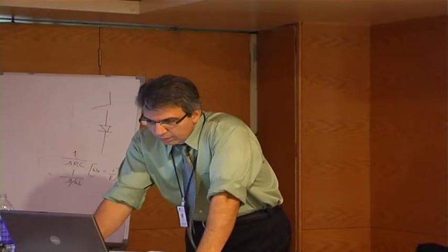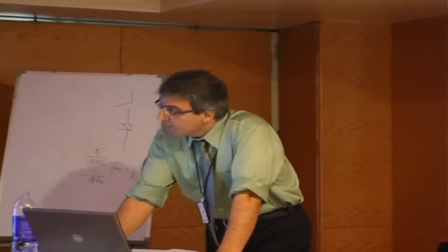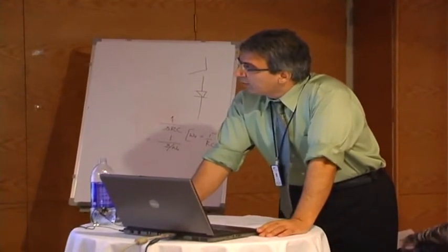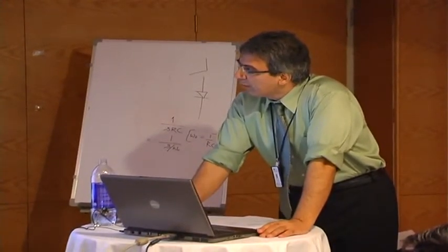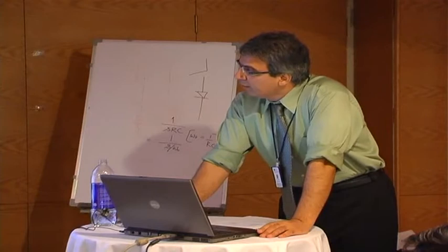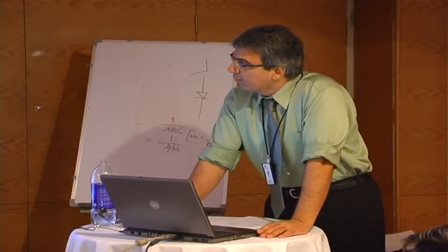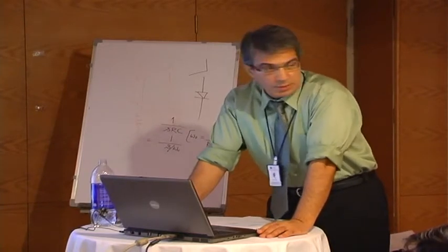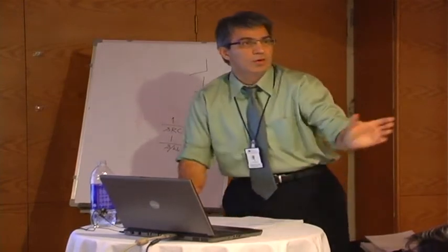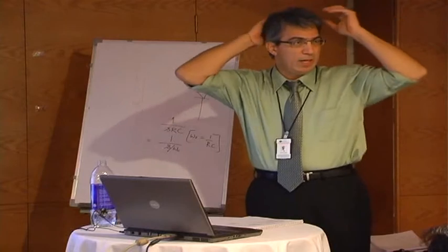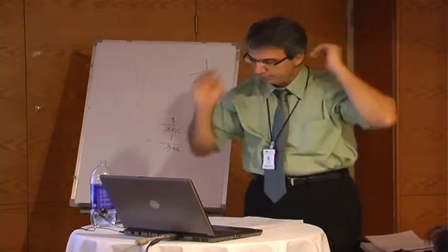Now we have a simulation profile here, and we're running a transient analysis. We can run DC sweep, AC sweep, bias point, but here we're running a transient analysis, and we have set the runtime to 20 milliseconds. We start collecting data after 6 milliseconds. And the maximum time step is 5 microseconds. So again, our switching frequency is 50, so the maximum time step we allow is 5 microseconds.